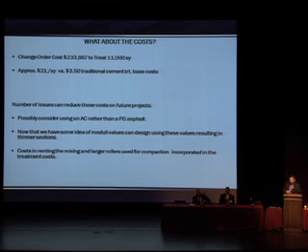There are some things you can look at as far as reducing the cost. We use a PG binder 6422. You could possibly look at using an asphalt or even an emulsion. We had issues getting asphalt. We were doing it in the heat of seal coat season, so getting asphalt was an issue. So they gave us a pretty good price.